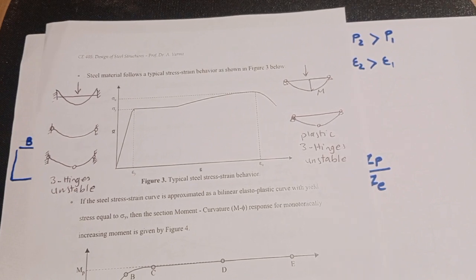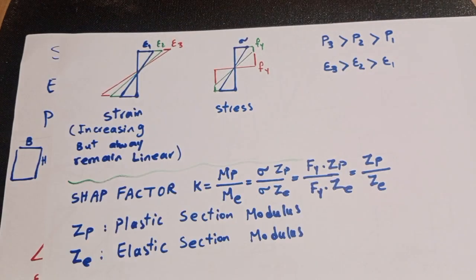The plastic range means that the structure can take much more loads and absorb loads, and it can deflect more, or technically we say that it has much more ductility. And here from that equation we can see that the MP value is higher than the ME value by a multiple of the K factor. K is the property of the characteristics of the section, and it is unique for each section.